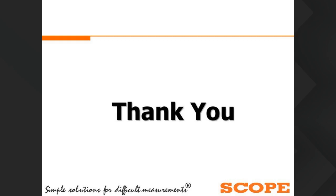With that kit, you can do not only demagnetization but also the knee point voltage test of the CT. So you can use MACD or the TRM, or even for standard demagnetization, a simple variac can also be used. So this is in short how we can do the demagnetization, and why we have not given the demagnetization feature inside the TTRM kit.